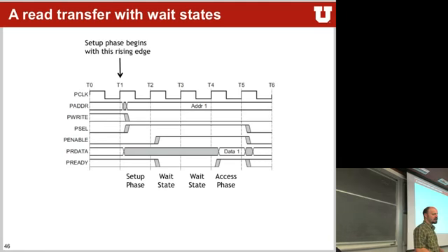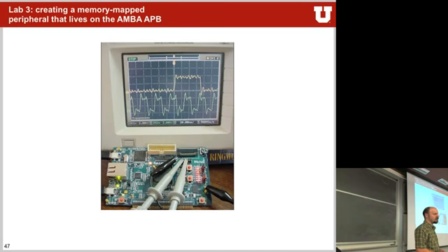And you will learn all about this particular bus in lab number 3, where you will also hook up to parts of the APB bus through some of the pins. Yet again, we don't have enough I/O lines to get the whole bus system out to look at, but at least some few lines you can look at and measure to see what's really happening with the clock and the data, at the select lines and enable lines on there. All right, any questions?